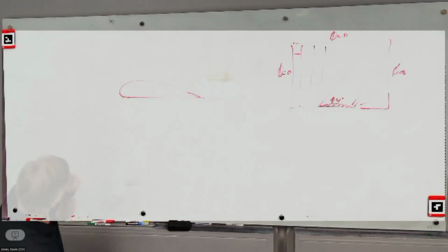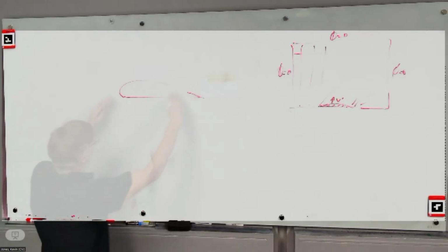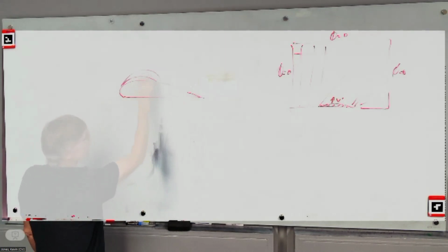And even more interesting is that when it happens, if you remember that video we showed of the two airfoils, one was laminar and one was turbulent. It's a trick question because it looked like the laminar one was actually turbulent. So it turns out that stall takes some amount of time to happen. If you were to crank this thing to an angle of attack, what you'll see is a big separation bubble will form, and it'll get bigger. There's like a vortex that's stuck in here.